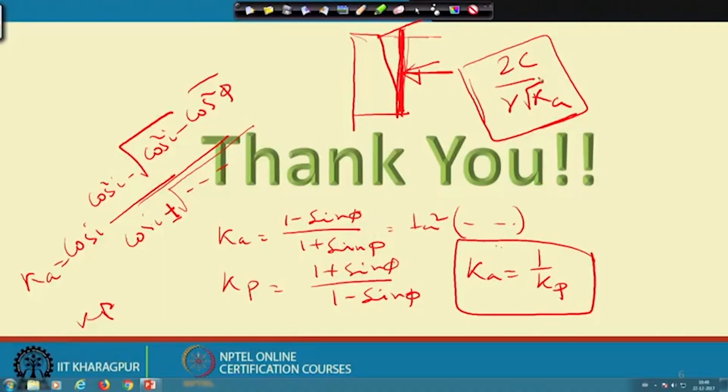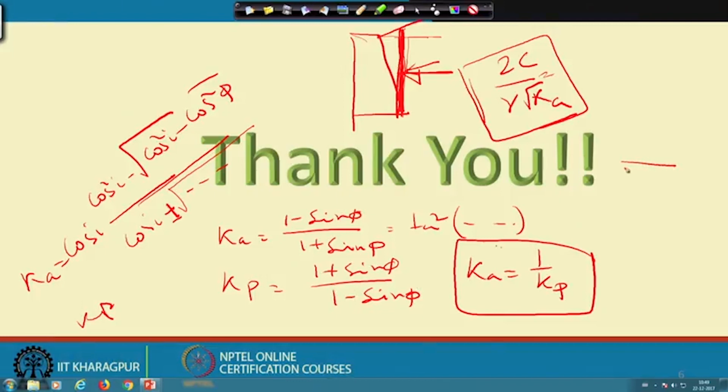If the depth of tension crack is asked, then this is the answer. If it is asked the maximum depth of unsupported excavation, then it will be twice that. How have we visualized it? The pressure diagram is like this, and this is the negative pressure. The total of this negative and the total of this positive become 0.